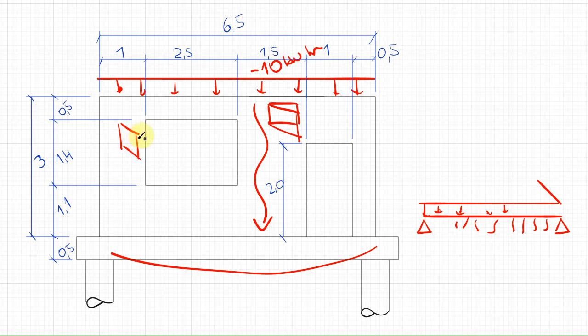That means the shear stiffness in the wall, which is used in the stiffness matrix as small d33, will influence the transfer of the forces, and we don't get so much force on the beam, and more of the forces will go to the bore piles.